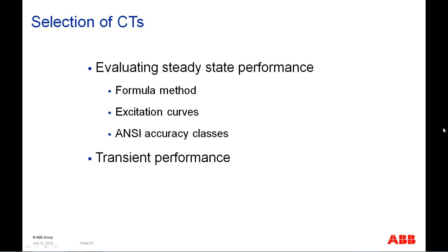What are the physical effects on the CT if 20 times rating is exceeded? Does the core get damaged? No, the core doesn't get damaged, but you start drawing a lot more exciting current. So 2 things happen. One is that the windings themselves will start to overheat when you get more than 20 times rated current through the secondary. And second, you'll start saturating the current transformer because of a large primary current, but it typically won't damage it unless the current gets extremely high. Hope that answers both those questions for you.